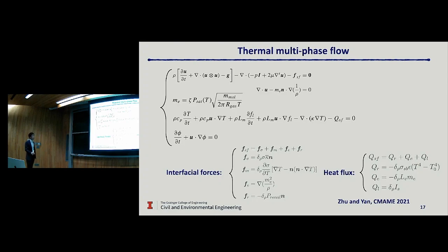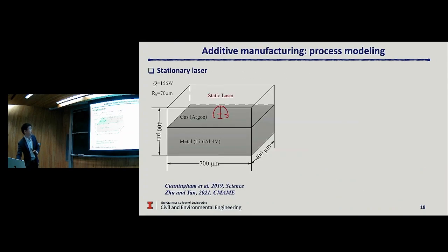And all of those boundary conditions are handled by the Brackbill continuous surface force model, which means all of those boundary conditions will be converted into body forces and enter the momentum equation, which actually has some issues. I will show you later on in my presentation. But right now, this is what it is. And then how we solve the PDEs: we are using a stabilized finite element method to solve all of those PDEs in a fully coupled way in order to achieve the best robustness.